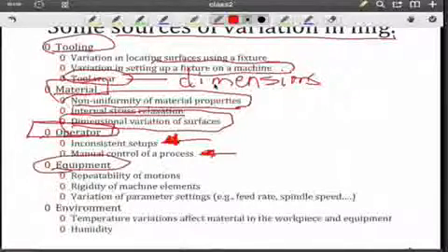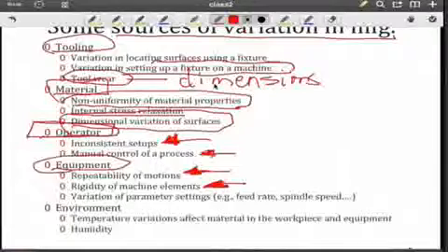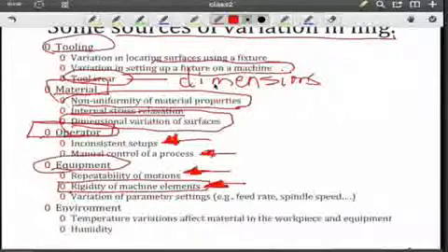If we look at the equipment that the operator is using, we note that there's a certain repeatability of motions. Every piece of equipment is going to have constraints in terms of how well it will be able to repeat a specific motion. And we'll see that later on when we get to the equipment aspect. If I look at the machine elements, so this machine has been designed to accomplish a certain task. However, parts of the machine have been assumed to be completely rigid, and that, in fact, is not true. And various components are going to twist and are going to bend. They're going to expand and contract with temperature, and so that causes dimensional variation if we're using that piece of equipment to produce a part surface.